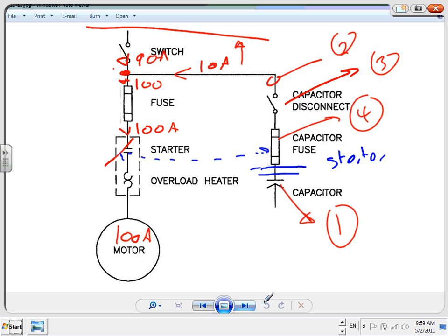I don't think they do them in buildings. I've never seen them in buildings. In buildings, you turn them on and turn them off, but you don't monitor the voltage. In utilities, they monitor the voltage all the time on the transmission line. If the voltage goes down, turn them on. If the voltage goes too high, turn them off. And there are multiple steps. They can turn on half of them, 2/3 of them, so it gives you close to the exact value that you want. Any question, guys, about this?